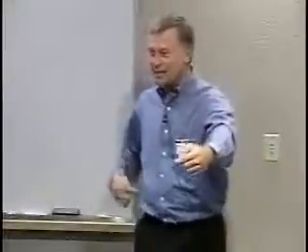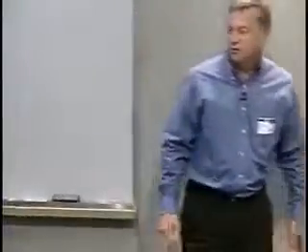And how does it know where the X is? It was told. It was told, you want to be over there at XY, and you're here at XY. Okay, so it has some kind of odometry. The question is, how does it know where it's supposed to go and how it's getting there? It knew ahead of time where the goal was, and it's counting its own leg strides. So it puts its leg on the ground here, and kinematically it says, I just moved 3 centimeters. And it does it again. Yeah, which was amazingly accurate, given we didn't expect it to be that good.